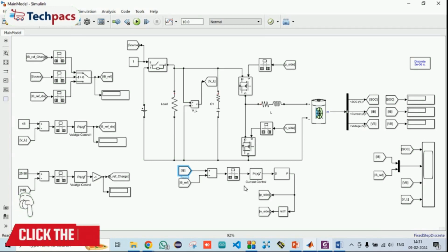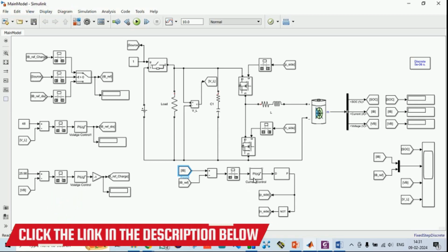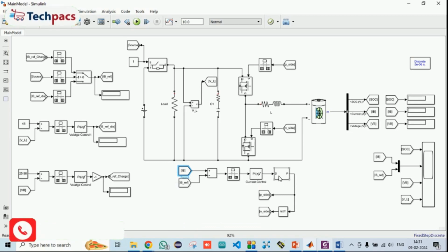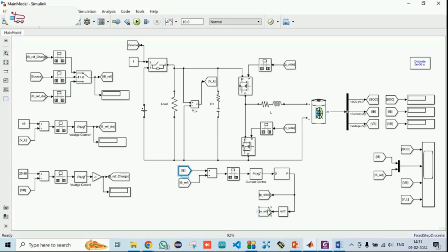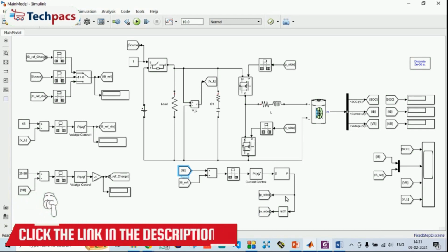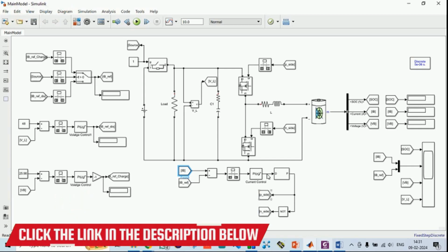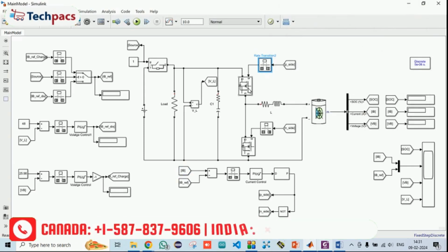One of the things that we have introduced in order to design the bidirectional DC to DC converter is the PI controller. This PI controller helps with the decision of generating the duty cycle, so that the PWM can give the input to the MOSFETs to switch on or off. This PWM is sending a positive and a negative signal, where positive is the direct input that we get from the PI controller, and negative is the inverse of the signal that we get from the PWM. This PWM input is given here, where this rate transition is sending the input to the MOSFET switch.